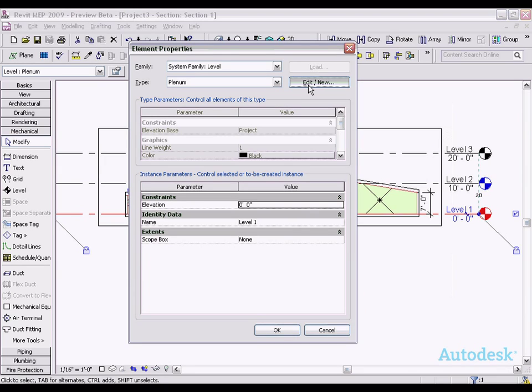In this example here, the 4-foot level actually intersects the roof, as we saw when we overrode the automatic setting previously. So in this scenario, one of the bounding walls is below 4 feet. And if that happens, by default, the automatic setting will modify the height to set it at 0, so basically right at the level itself. So that's why we're still getting a proper definition of volume here. Now with that understanding, we can go ahead and look at more complex situations where manipulation of this setting can be very valuable.